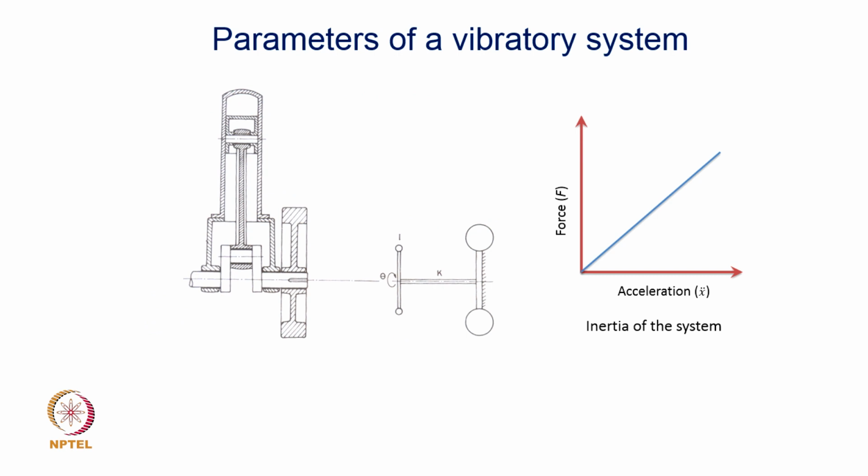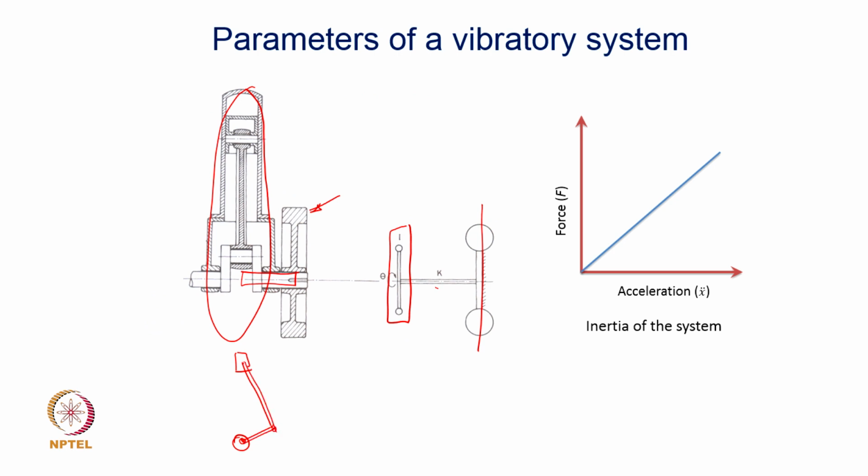The example I am taking is of a simple IC engine where a flywheel can be treated like a huge mass which can be treated as fixed, and this shaft can be treated as your stiffness element, and this entire mechanism, crank, connecting rod and piston itself, is your inertia in a torsional vibration setting. This entire mechanism is like an inertia at the tip of this crankshaft, right. So, one can find out what the stiffness is, but when you look at the inertia, this is a mechanism which has a moving piston and an oscillating and rotating connecting rod and a crank here.